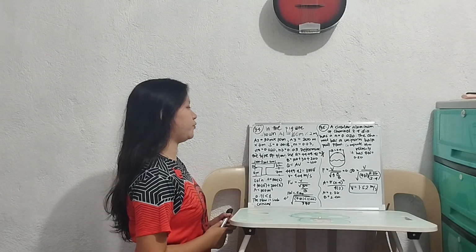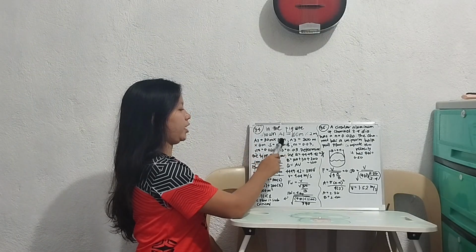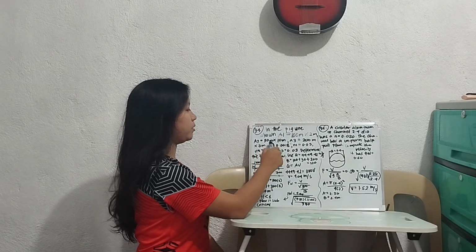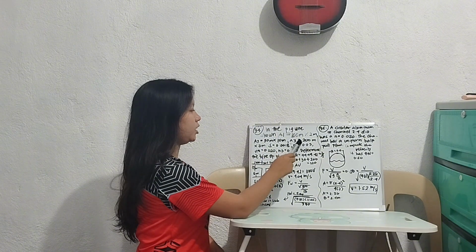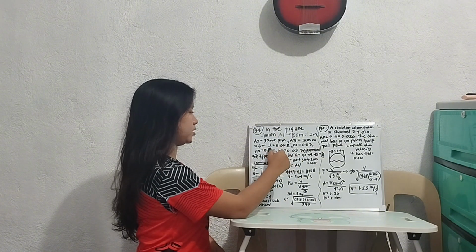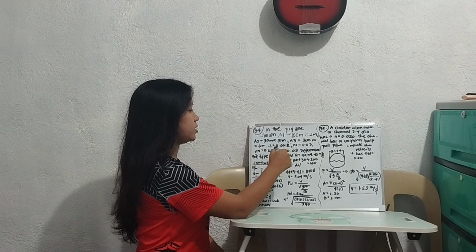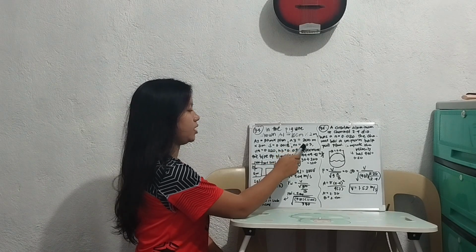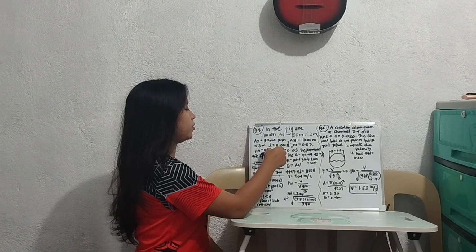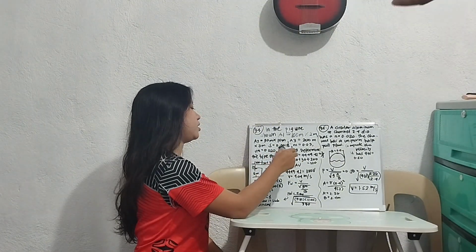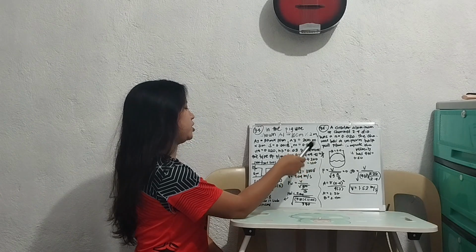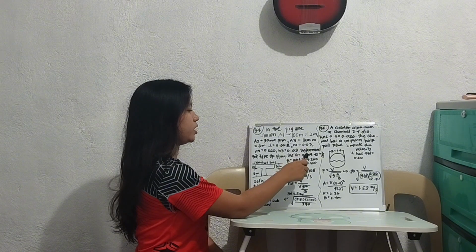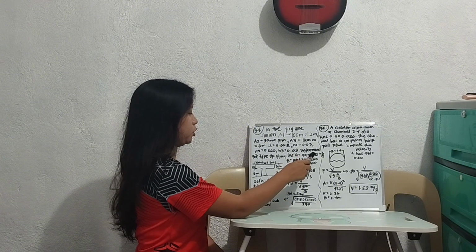Okay, so for number 34, in the figure shown, area 1 equals 100 meters by 2 meters. Area 2 is 30 meters by 10 meters. Area 3 equals 200 meters by 3 meters. And the slope is 0.0018. And then N1, or the roughness coefficient, is 0.03. N2 is 0.020. N3 is equal to 0.03. So determine the type of flow, then use the discharge equals 4,449.42 cubic meters per second.